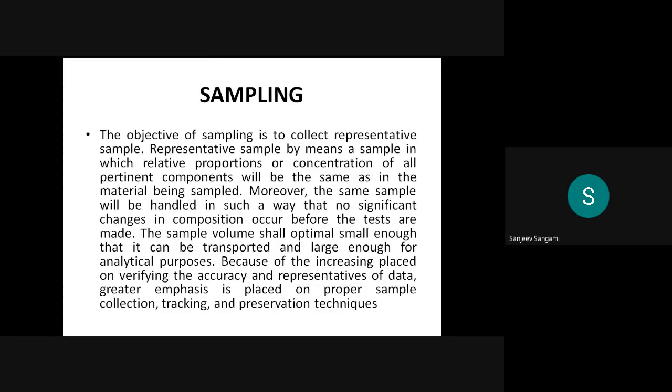So the objective of the sampling is to collect the representative sample of what is there in the sewage. A representative sample means a sample in which the relative proportions or the concentration of all the pertinent components will be the same as in the material being sampled.